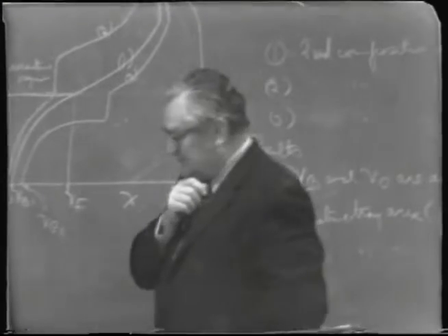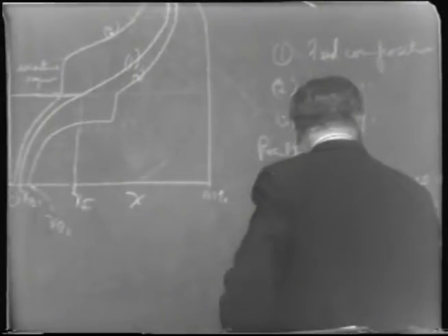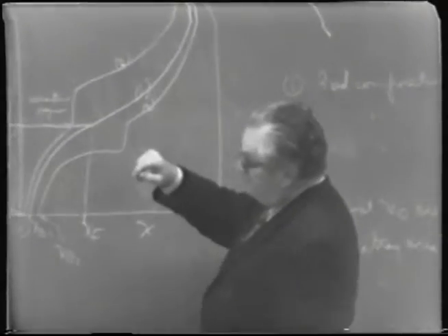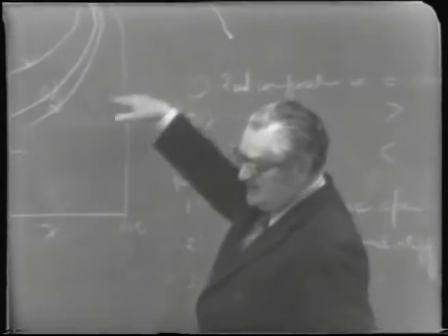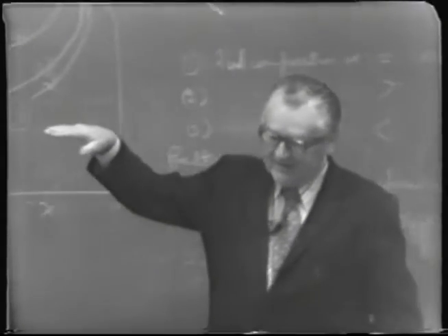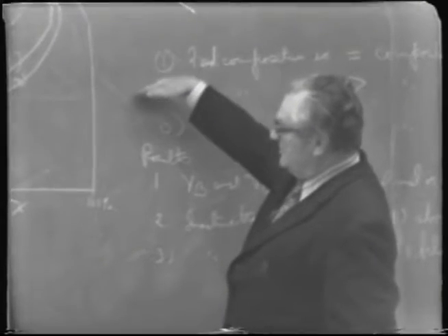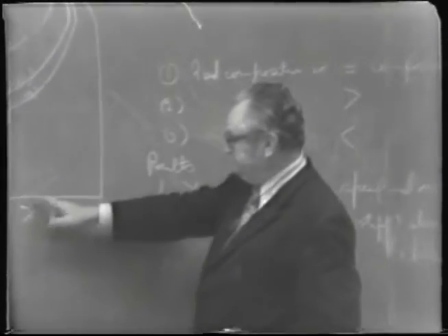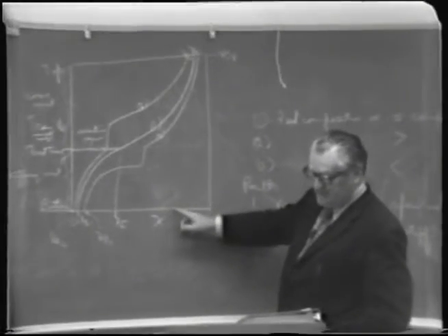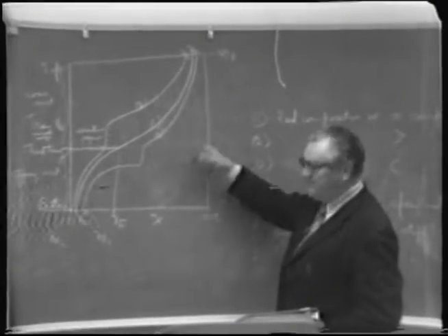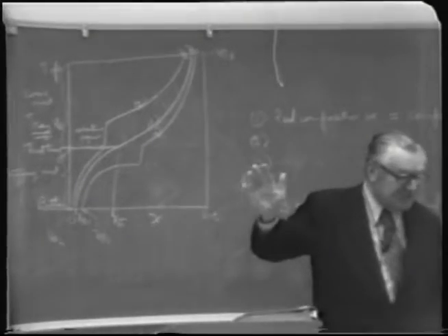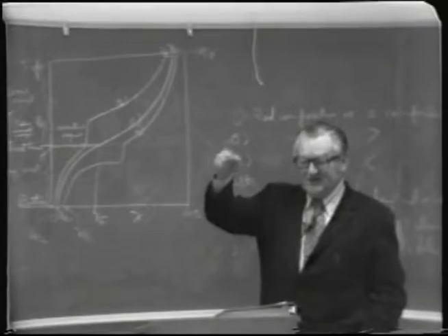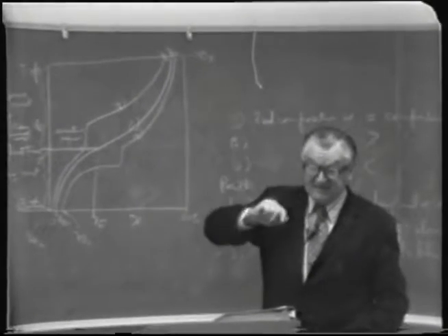This means then that with a goodly number of trays, much more than you need, you can have a situation where you draw the product off at, let's say, 85% by volume, and the heads would be 192 proof. You've got a good number of trays to concentrate the heads.